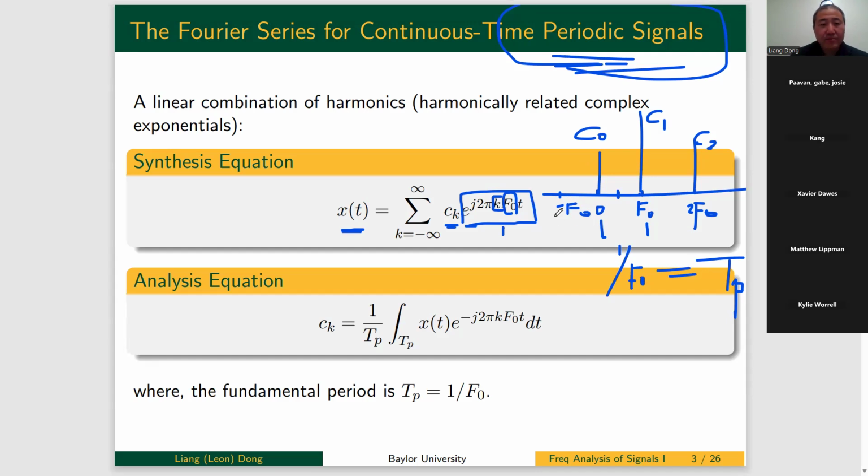We memorize the Fourier transform very easily. We have this, which we call the synthesis equation. You have an arbitrary signal, you decompose it into a group of harmonics. It's a linear combination of these harmonics. For those coefficients C sub k, there is a way I can calculate them. Mathematically, I can solve for that. And C sub k is equal to this.